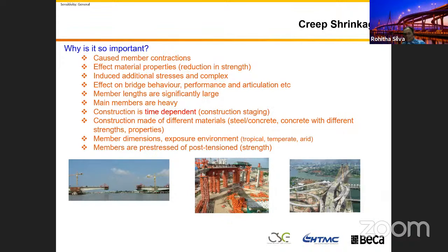And the other thing is that creep and shrinkage parameters differ when you use different design codes. For Australia, the design standards say you have to use these parameters, but Eurocode develops general parameters.